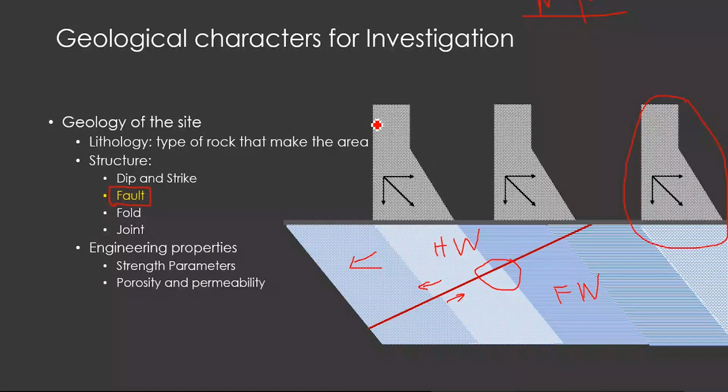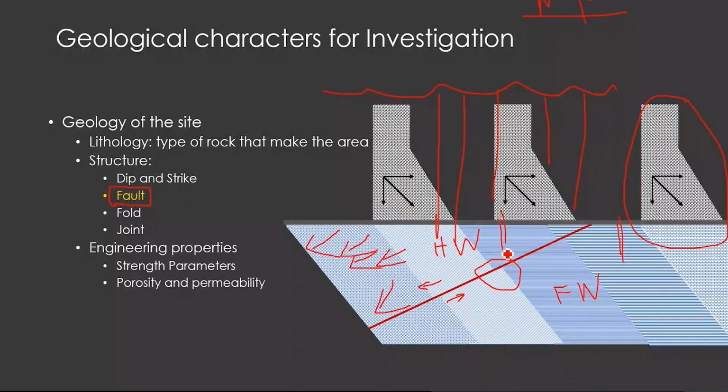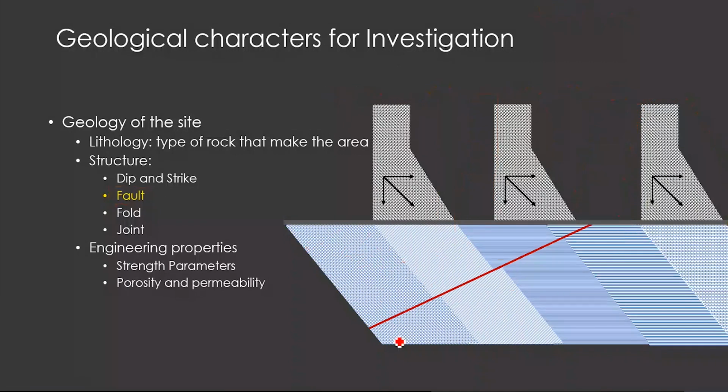But in this case, the trouble is that the reservoir is here. It is going to exert a lot of water pressure in this region. These forces exerted by the water pressure may give rise to some movement on this block. There is a change in the relative stability, because this area is stable, but this area is not that stable considering the rock type, because the dam is going to be on the footwall. Now the second situation is again the same, where we consider the region on the hanging wall. This again has the same trouble.